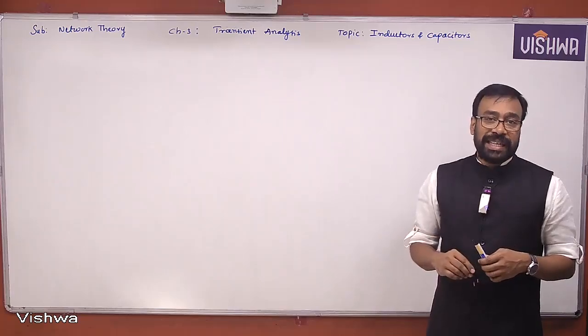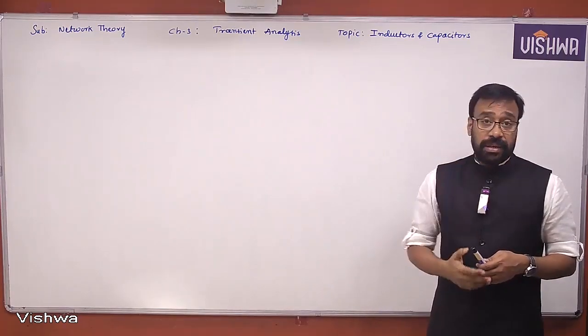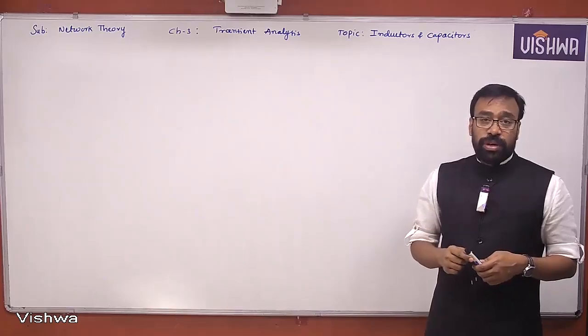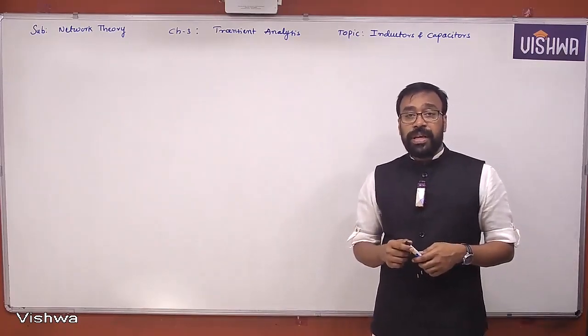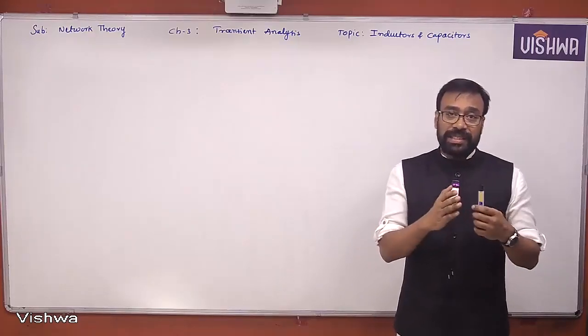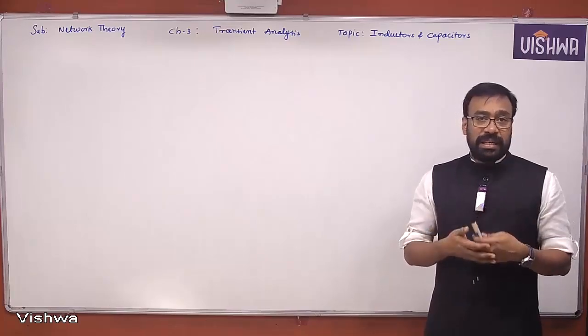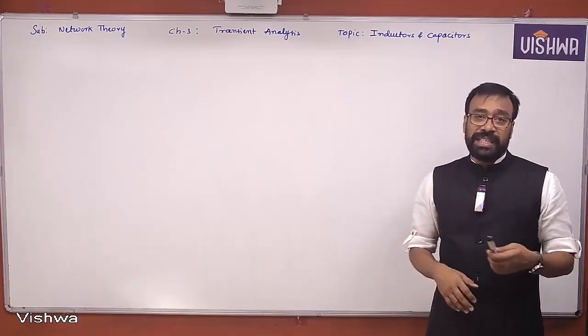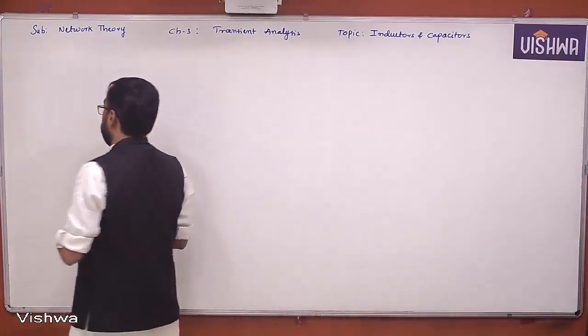You can find what is the Z, that is impedance. Okay, magnitude of impedance you can calculate if you know the AC source voltage as well as frequency. Along with the frequency, if you can note down, then you can find the L value easily, because you know that XL is nothing but root of Z square minus R square. Once you know XL, you already know frequency, L can be easily determined. So this is how you can determine the choke coil parameters.